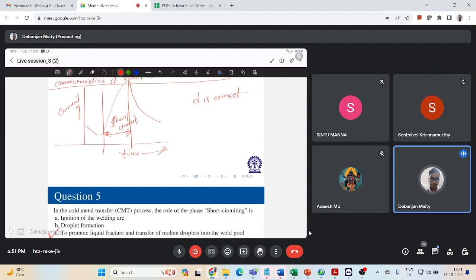Now, coming to the different kinds of additive manufacturing processes, you have fused deposition modeling, powder bed fusion, and so on. In powder bed fusion, the power source first melts the layer of powder that is sprayed in the container, which is vacuum sealed or filled with inert gases to make sure the powder particles do not react with the atmosphere.